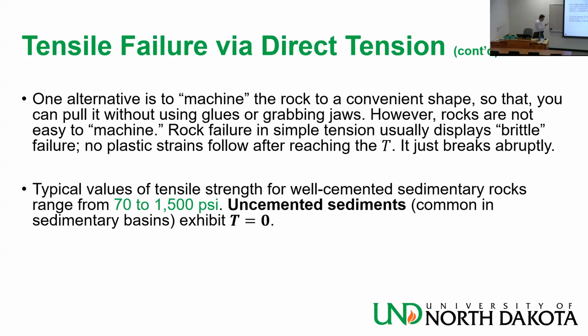That's why Nassim, my undergraduate student who's working on fracture initiation, writes models that check whether T is exceeded. And after that, those models are no longer valid because you have created a fracture. Then if you want to create a model for, say, fracture propagation, you need to be able to have your model incorporate the discontinuity in the system that is the fracture. That's why we say fracture initiation is not the same as fracture modeling, like fracture growth modeling or propagation modeling.